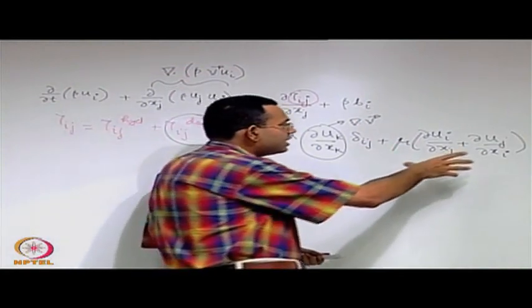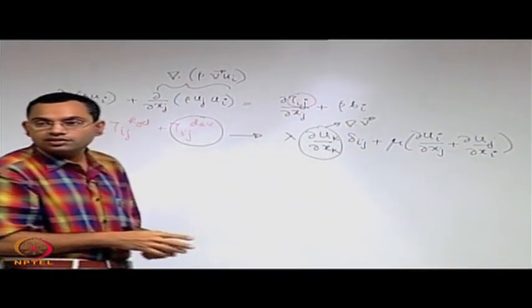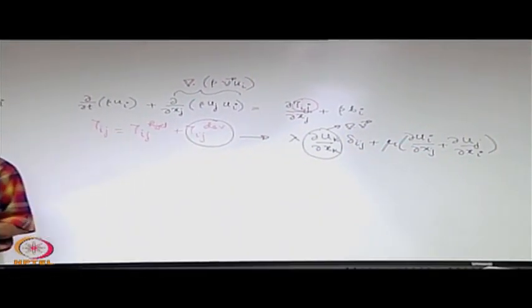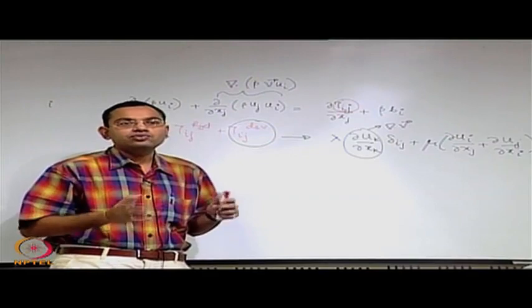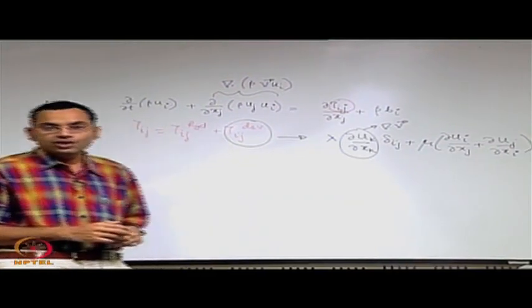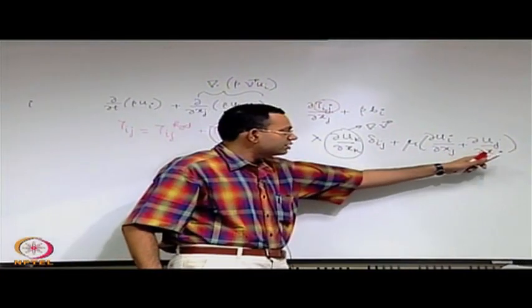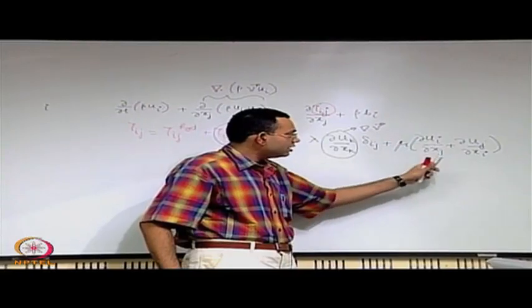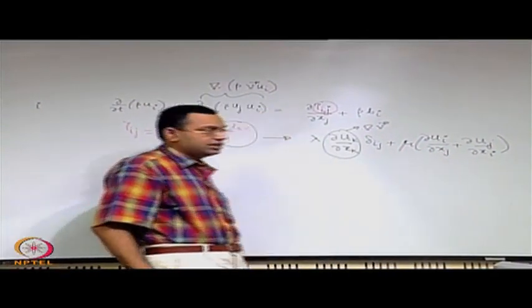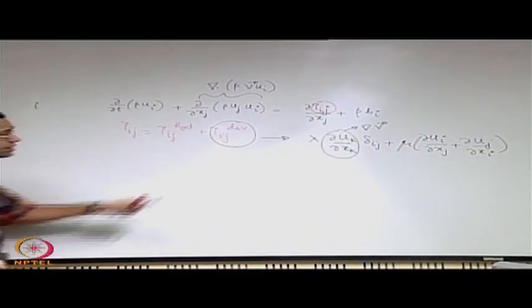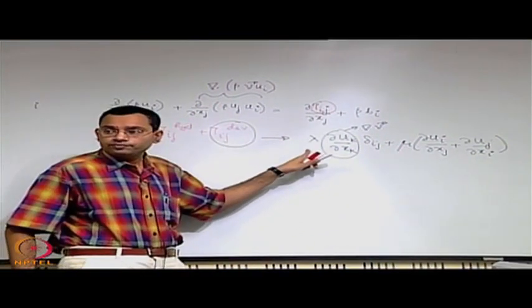And regarding angular deformation, we have seen that it is the shear deformation that matters for the stress, because the rotational component is an effect that does not give rise to any viscous stress. So only the symmetric part of the deformation is going to give rise to the viscous stresses. What are the assumptions under which this is valid?